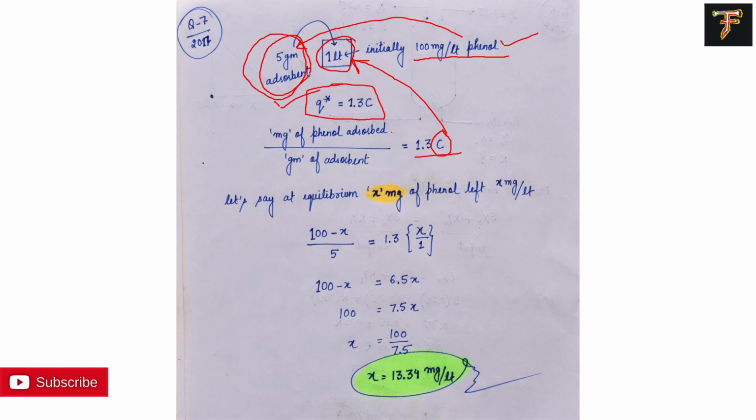Now this is a batch system. So let's say at any point of time, out of this 100 milligram, X milligram of phenol is still left in the solution. Then 100 minus X has been adsorbed, right?